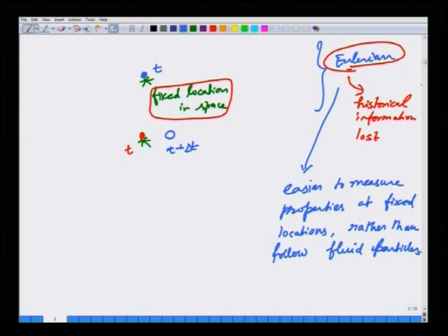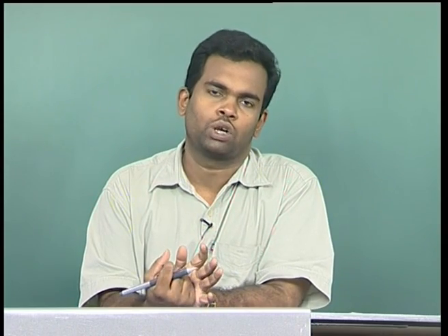Okay. So, in fluid flow problems there are two reasons why Eulerian description is preferred over Lagrangian description. Firstly, even if it were feasible, having the information about what are the various fluid particles that are occupying, let us say, a given section of pipe is really not relevant to many practical questions such as what is the pressure drop, because here we are not really worried about which fluid particle is coming and exerting a drag force, or we are merely interested in the force that is experienced by the walls of a pipe or a sphere that is moving and so on.